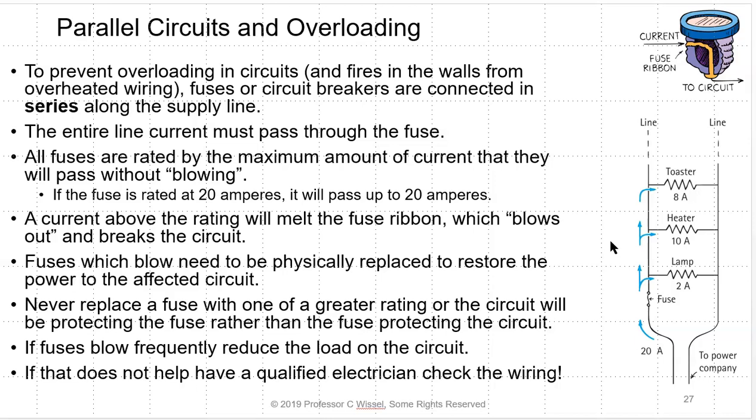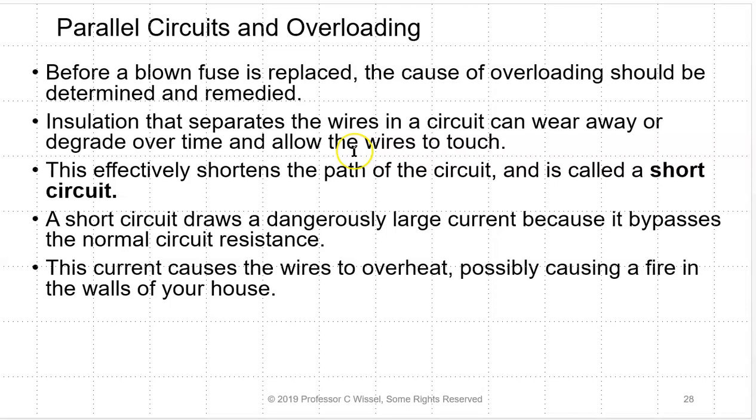If fuses blow repeatedly, reduce the load on the circuit. If that does not help, have a qualified electrician check the wiring. Before a blown fuse is replaced, the cause of the overloading should be determined and remedied.